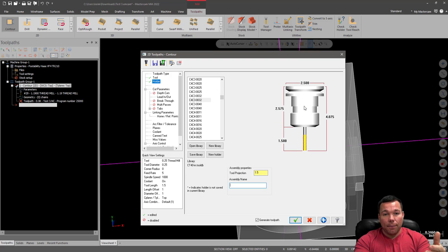The other way, coupled, when you create an actual tool crib with the correct speeds and feeds, the correct tool numbers, that coupled along with setting your operation defaults really, really decreases the time that it takes to program parts. So I believe that's all I have.